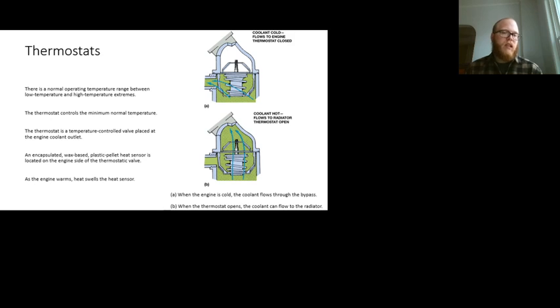be around 210. Because when we're up to full operating temperature, right, 70 degrees was when emissions compliant stuff starts happening, but the engine's actually at operating temperature as far as best combustion quality goes at somewhere around 190 to 210 degrees Fahrenheit. Anything colder than that, we're not going to get full combustion. Anything hotter than that, then we might start to create some gases like oxides of nitrogen that we don't want, or maybe even start damaging the engine as the piston starts getting too hot and swells up bigger than the hole of the cylinder.